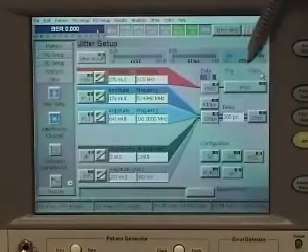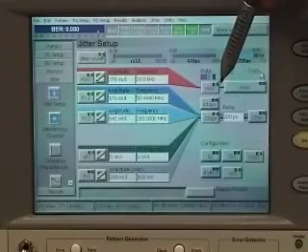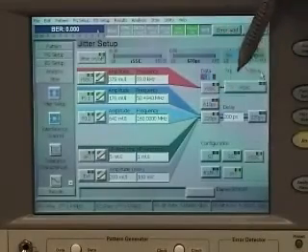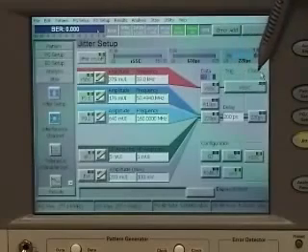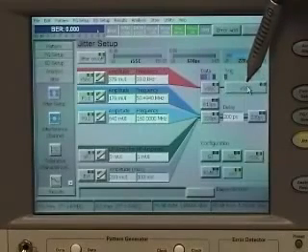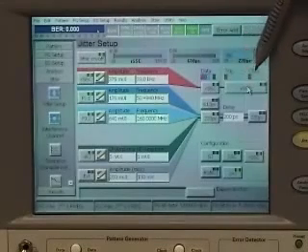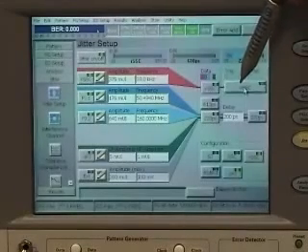Here in this area, you can choose if you want to have the jitter just on the data signal or also on the trigger and the clock output. So now I have turned on the residual SSC also on the trigger output and the clock output.